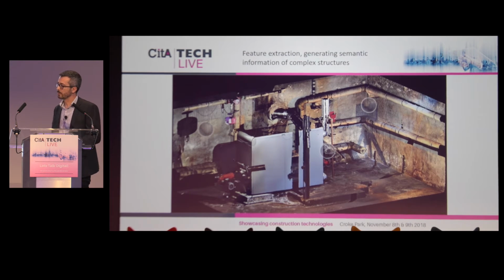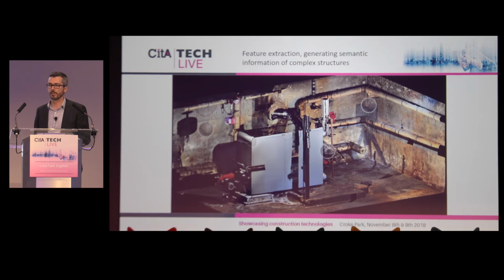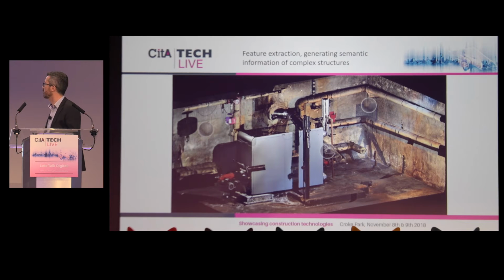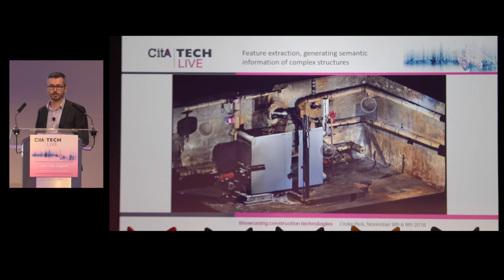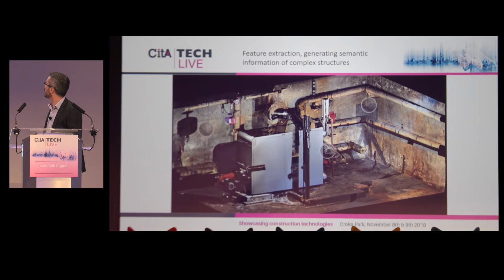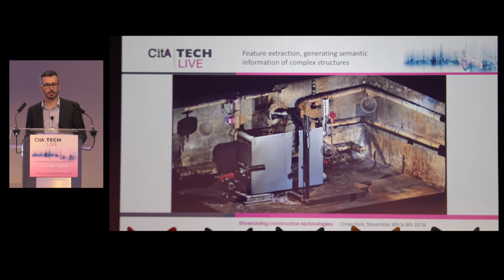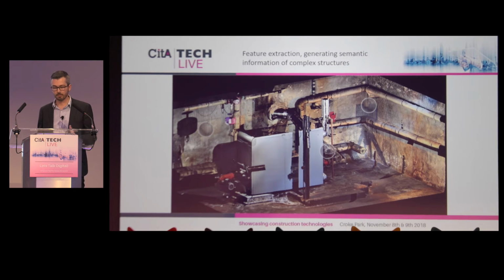That works very well if the structure is regular, but in our business, we often need to measure buildings that are 50, 60 years old, maybe more, and we find that sometimes the scenes we see on site are somewhat chaotic. There are no flat walls, there is insulation material on the pipes, there are data voids in the point cloud caused by objects that create shadows. So the point cloud data is sometimes, or I would say often, incomplete.